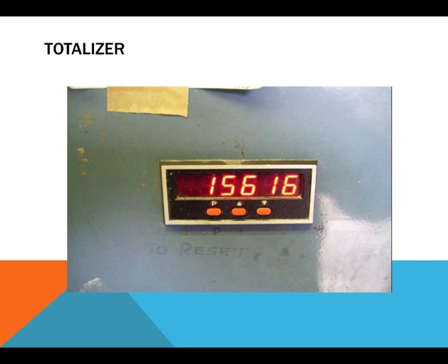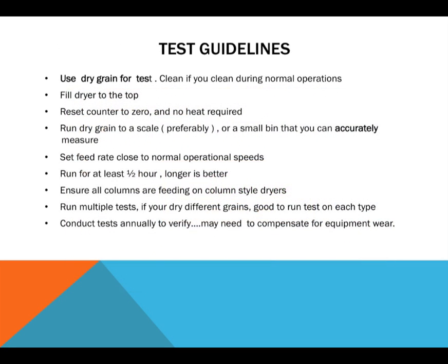And this totalizer, we would start in the morning with the totalizer at 0. And it would sit there and count. This actually counted one of 10, so every 10th actual revolution, it only counted 1. You can set that up depending on how fast your system operates. So you would take that, and this would be the total for the day.